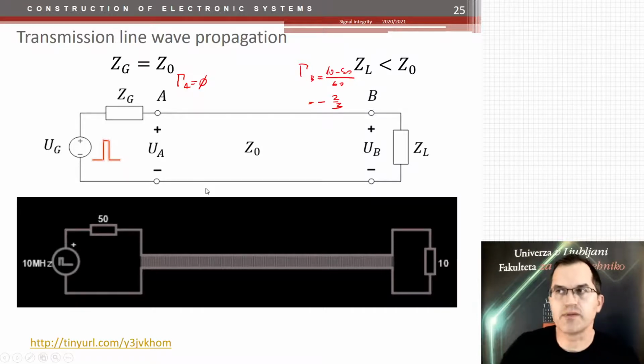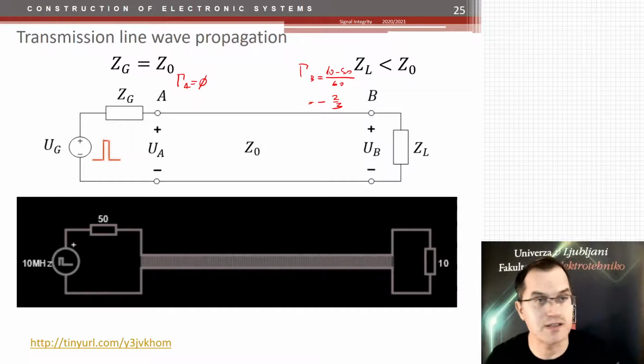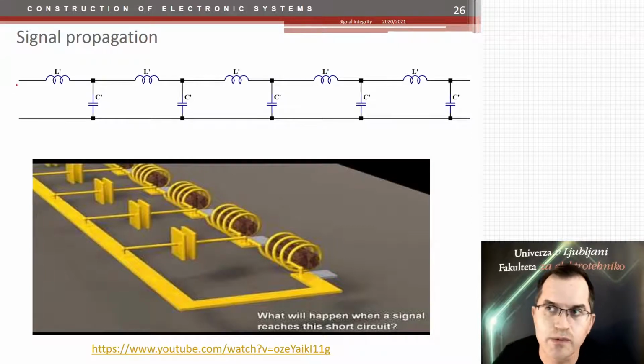All that signal propagation with the positive and negative reflection coefficient needs a little bit of extra explanation, I suppose. Because how does that work? The easiest way to show it is actually to try to mimic the signal propagation with this LC circuit. So we have a pulse that generates here, and let's say you're just turning on the voltage. So we have a 0 and we have logic 1, and then we keep it.